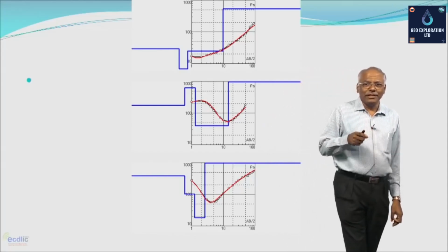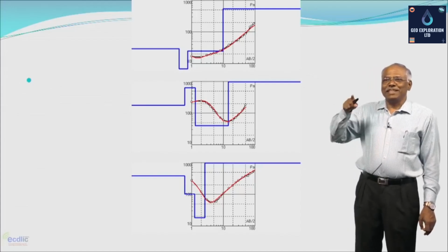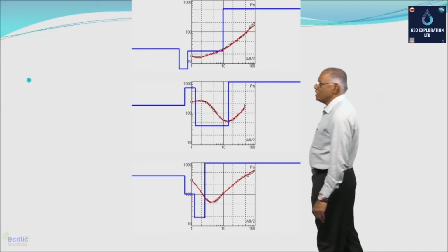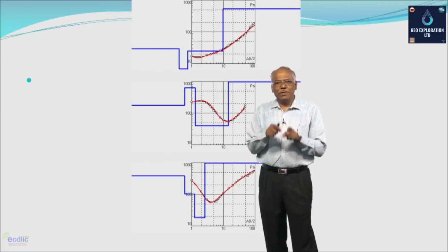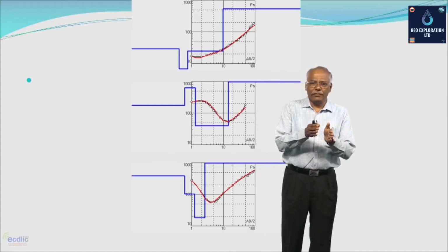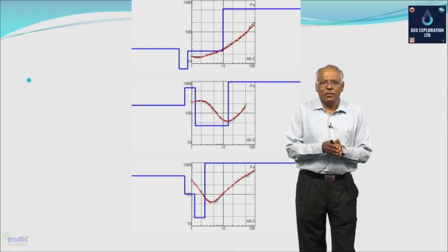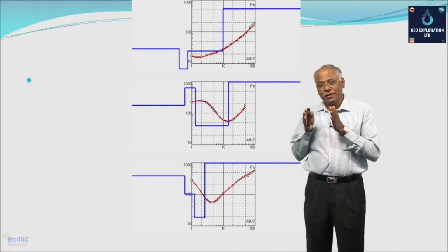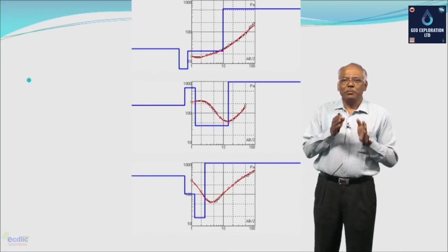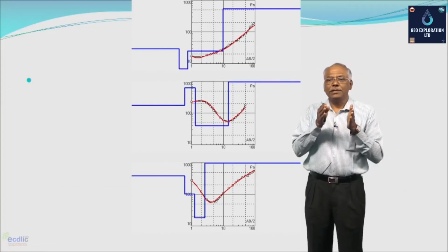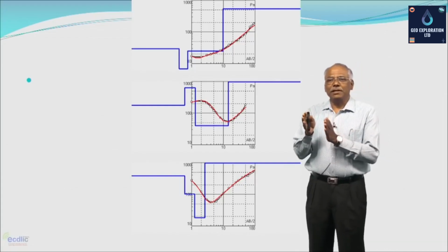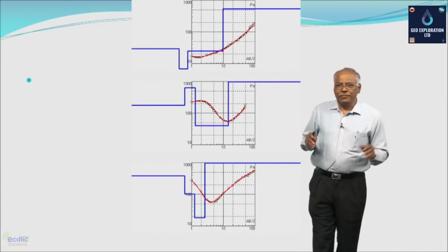Means your rho 1 is greater than rho 2 is less than rho 3, and therefore, you have typically what is known as an H type of curve. An H type of curve indicates that there is a resistivity low at a shallower depth. This is a typical scenario if geologic or hydrogeological conditions favor it, which means you have the possibility of getting groundwater at a shallow depth, an ideal situation for tapping the water by taking a dug well.